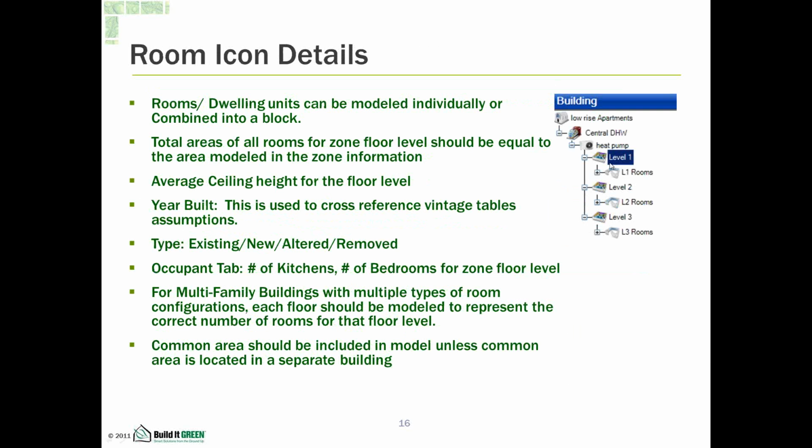So after we build out our zones, we're going to build out our rooms, and these rooms are going to be represented in blocks. They're not going to be each and every dwelling unit. You can do a unit by unit analysis, but if you have, hypothetically speaking, 139 units, this is going to take you a very long time to build out, and the person who's going to be reviewing the model is probably going to feel like it's pulling teeth reviewing that kind of level of analysis.